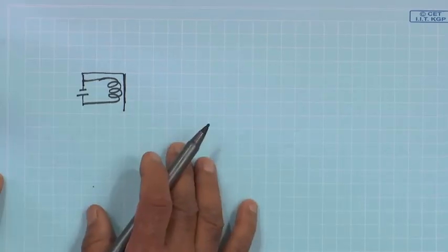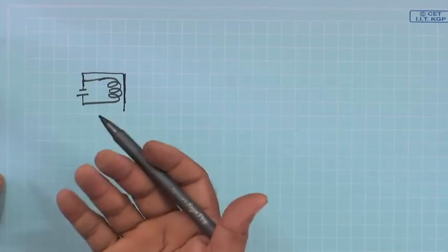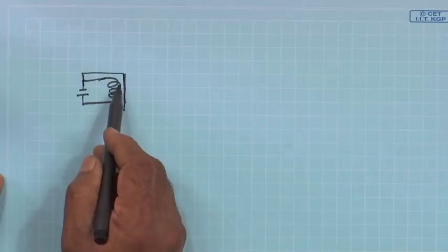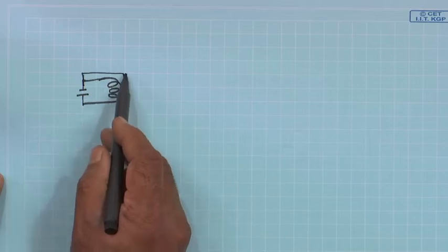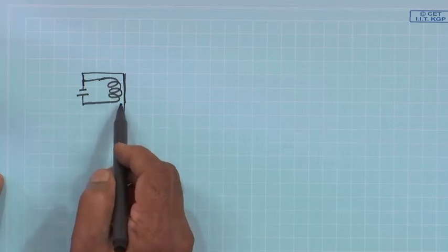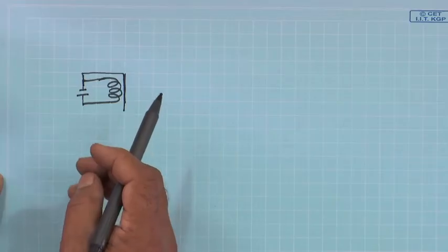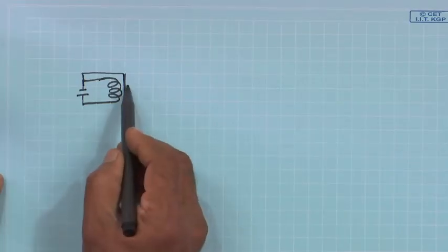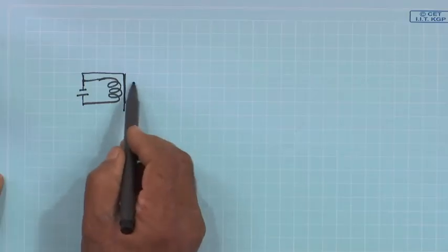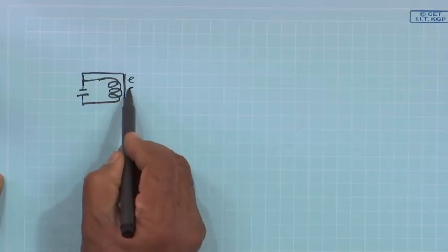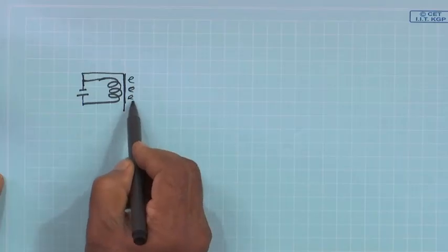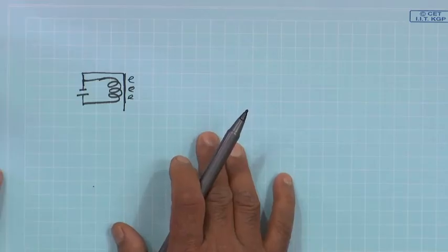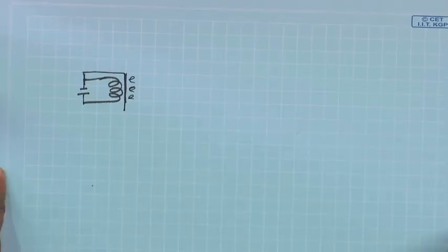So, it is the cathode with lower work function. The electron emitted from this filament will hit this cathode. The cathode has a low work function, so from its surface a lot of electrons will come out. Basically, you can call this a thermal emission kind of thing. So, a lot of electrons will come out.